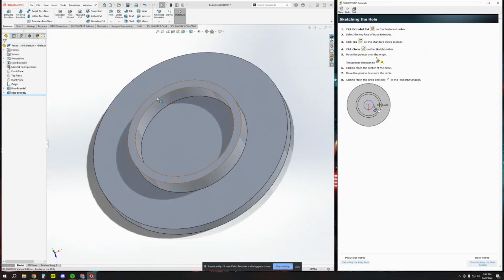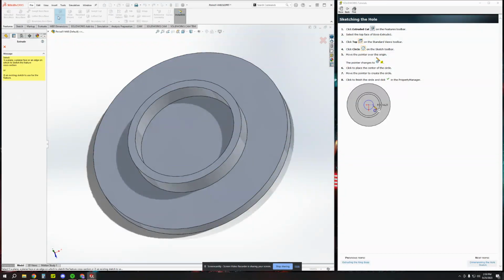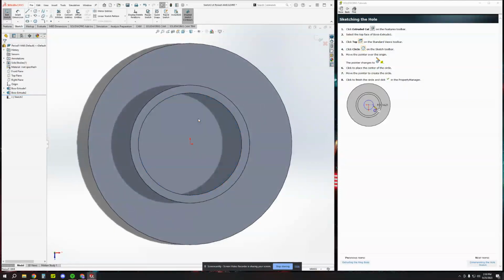Extrude cut. So when we're making models, we can't subtract from nothing. So we always have to make something first. And you can add on top of it or you can subtract away. So let's go on to our next function. We use this a lot. It's called extrude cut. So if you click the icon, you'll see there that it makes it flash, extrude cut. I'm going to click that. We're going to make it on the same face right here in the circle.